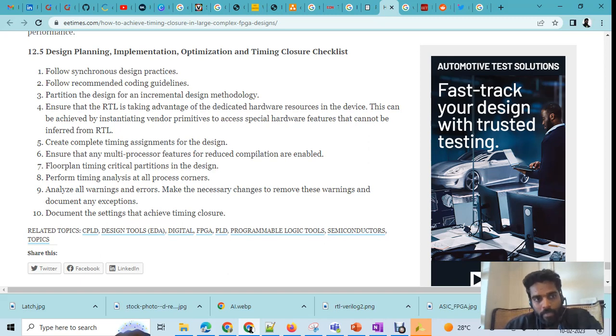And if you have multiple clocks, then you have to identify those and work with the design team. You have to write a separate constraint for them. Otherwise, the tool will end up wasting a lot of time doing timing analysis for that also, which cannot be done, but the tool will try to do that.